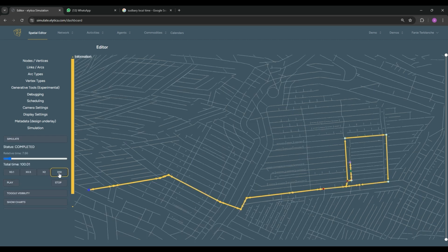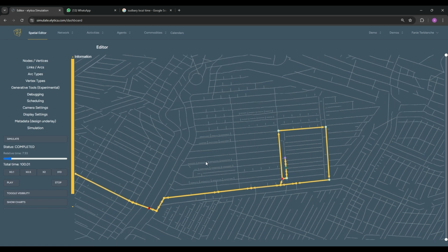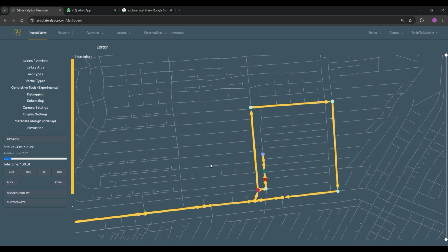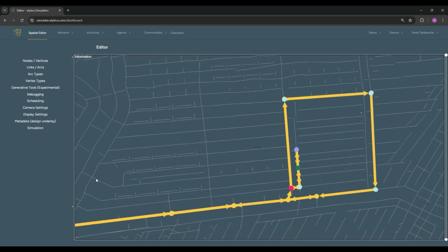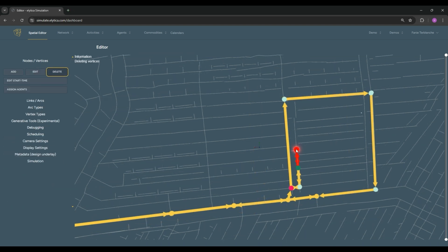The animation results show how loaders move material from the source node to a loading point, and how trucks move from the loading point to the tipping point. The limitation of this model is the inability to capture the increasing travel distance of a loader as development progresses further into the area. To address this, the material source node is removed and replaced with explicit links that represent